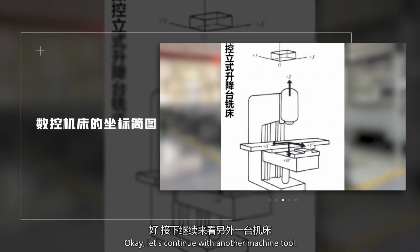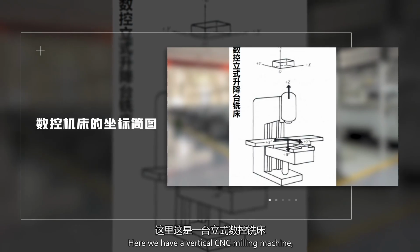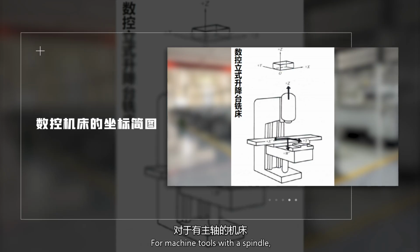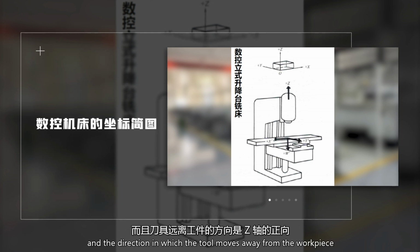Okay, let's continue with another machine tool. Here, we have a vertical CNC milling machine, which also has a spindle. For a machine tool with a spindle, the direction parallel to the spindle can be chosen as the z-axis, and the direction in which the tool moves away from the workpiece is the positive direction of the z-axis.